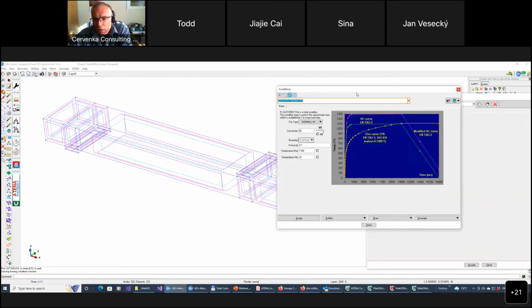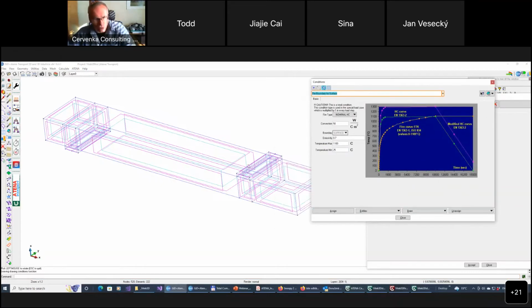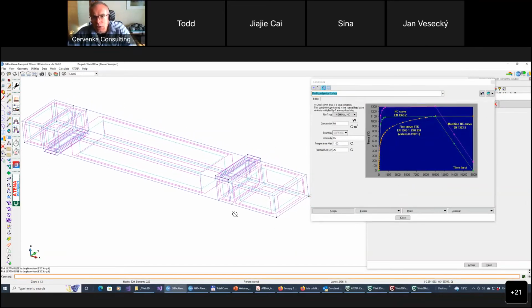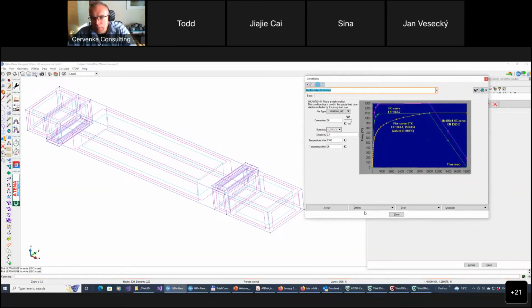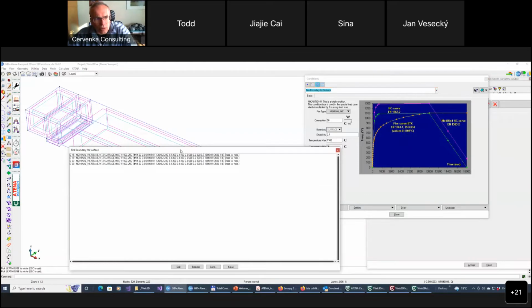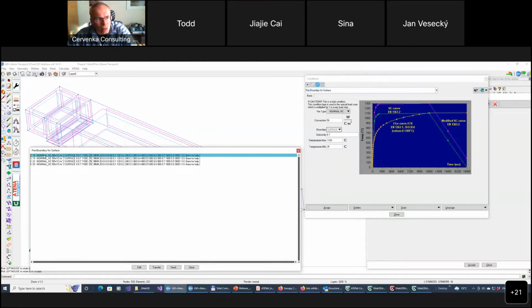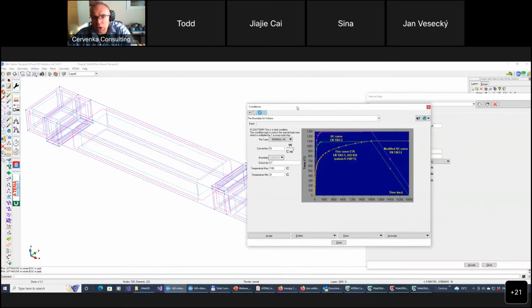So we can now describe the various options we have here. You see this is the typical input data for this dialog. If I want to see what conditions are defined here, I can open these entities, and you see I have 4 conditions here. Let me transfer them so that I can show them more in the window. So we are using this nominal hydrocarbon curve, which is, let's say, a standard Eurocode curve for fire in tunnels.